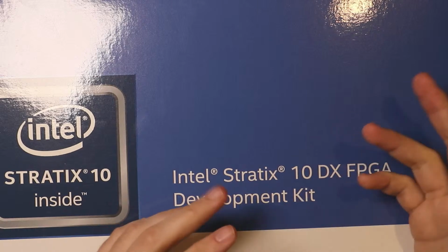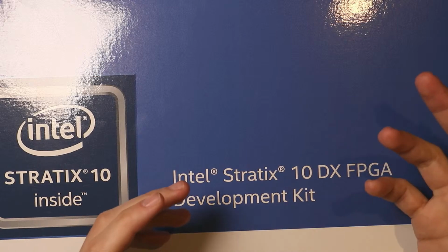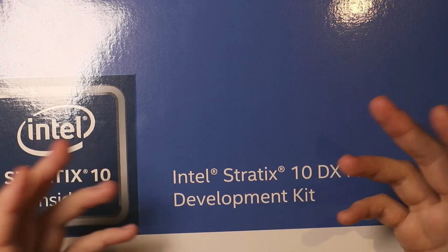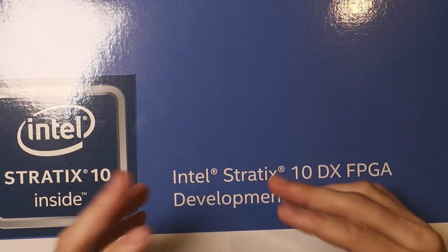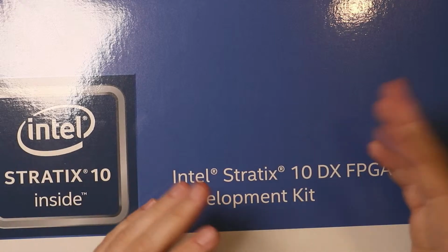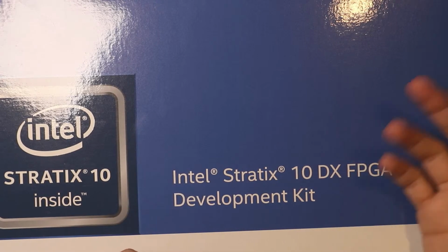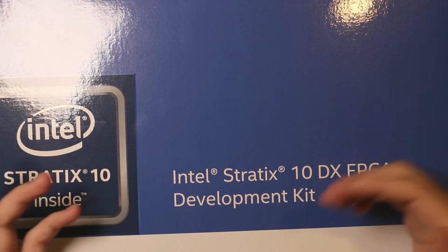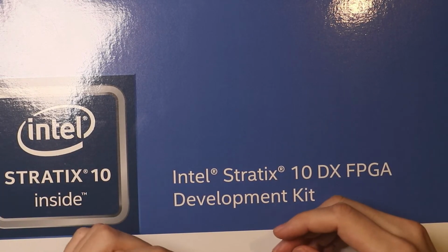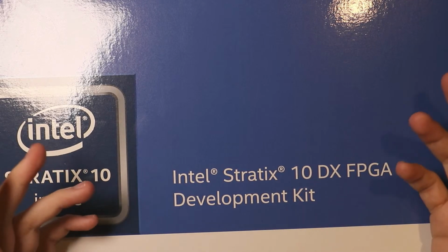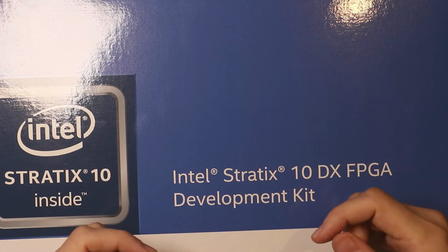That's one aspect. Another aspect would be maybe ecosystem considerations, right? If you have a big code base that uses Intel IP cores or Intel QSys, or maybe the Xilinx IPI flow, the block diagram flow, that can be very hard to port to a different tool chain. So that might drive the selection of a particular tool chain or a particular series of FPGAs over another, just based on kind of legacy considerations. Or maybe you really like OpenCL and Intel's OpenCL support is better than Xilinx, or whatever.